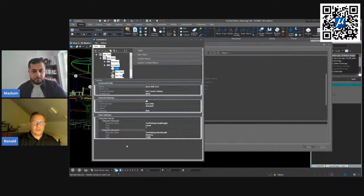And you can also add more settings. Sometimes we need locks for some reasons. There's a grid lock, or there's an annotation scale lock, also an orthogonal lock, to get only 0 and 90 degrees angles, whatever. Now, if you need these locks, you can set them directly at the tool. You can also set the snap mode.